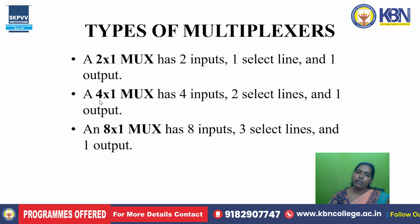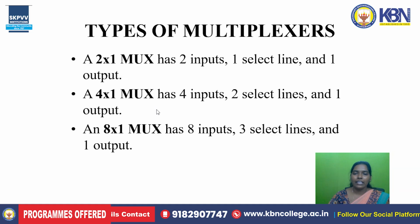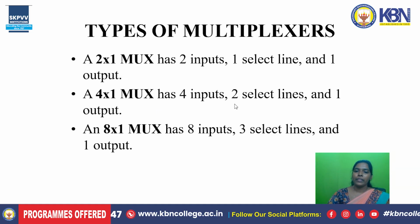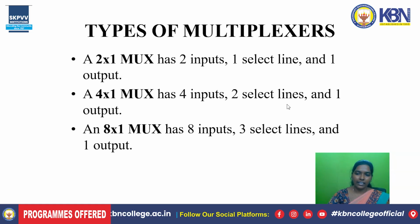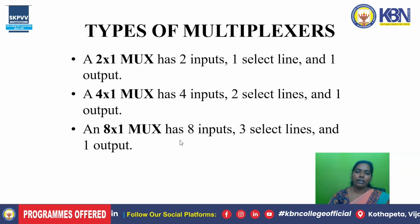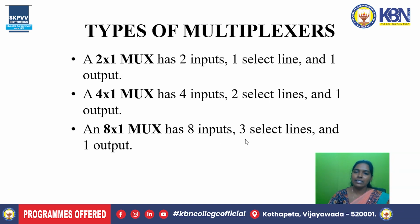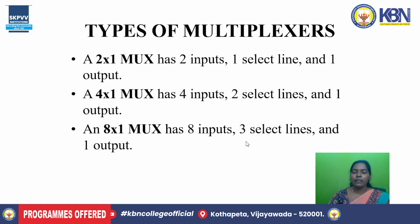Like that, 4 can be written as 2 square. The power indicates the select lines, that's why we are using 2 select lines. And coming to the 8:1 MUX, 8 can be written as 2 cube, so we are using 3 select lines here. That's why we can also use 16 by 1, 32 by 1, etc.